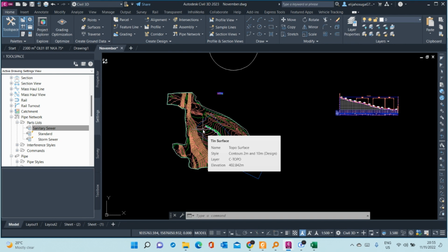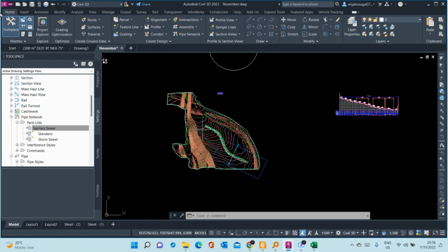Let's say you are doing your Civil 3D work and you find your computer very slow. You may want to use a very big surface from this drawing in another drawing, so that you do not overwhelm your computer with a lot of data. You can leverage data shortcuts to do that.